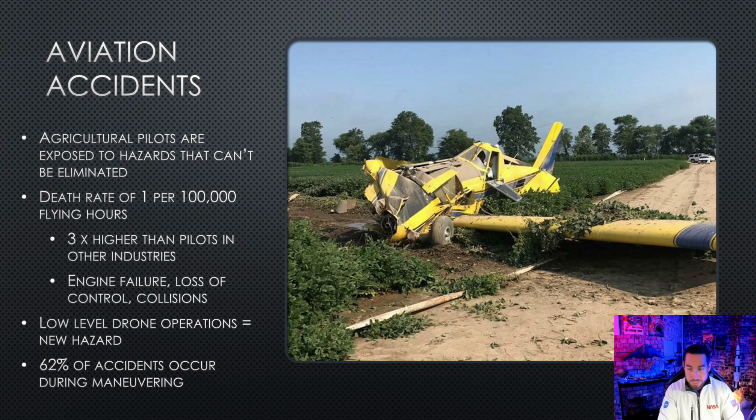Even though, as I mentioned, from the 60s on they tried increasing the reliability of engines, they never work with 100% reliability. There's always the risk of engine failure. A lot of it depends on your maintenance crew, how well things are being kept up, but there's always that risk. There's the risk of loss of control, whether it's due to control surfaces breaking or loss of focus. There's any number of things that can happen. And then collisions with things. And more recently, low-level drone operations have increased the risk. Even a small drone, if an aircraft sucks it into the engine, causes engine failure immediately. That's the equivalent of a bird strike, which can be deadly too.